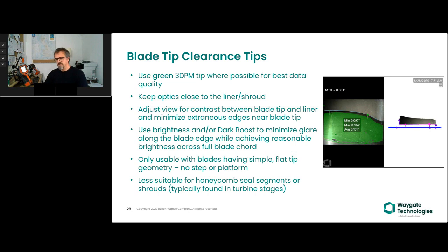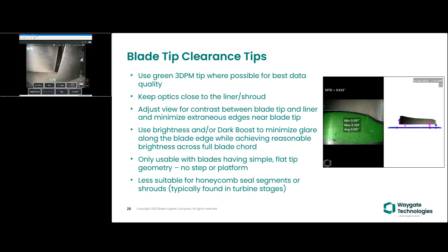So this is a measurement function that really does save a lot of time. Rather than doing individual depth measurements and then repeating those measurements on all of the blades, this is essentially a one-button process. So if I was just to now flick back to my borescope image, just one second. Just going to share with you my borescope screen and play a short video.